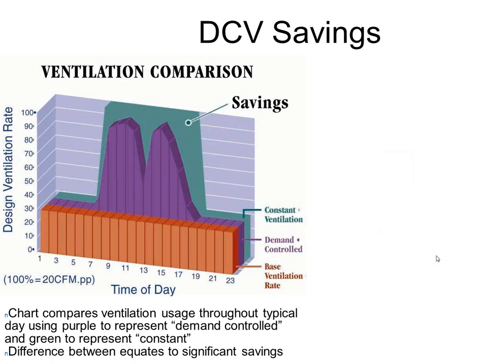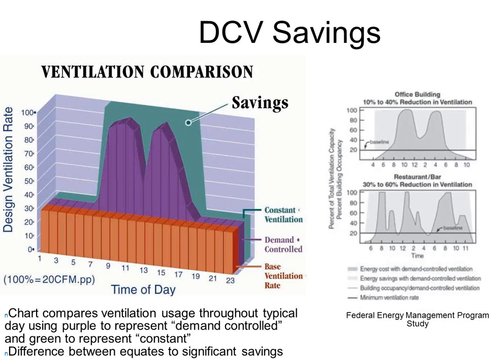This particular one that was on the screen is from a building down in Florida, but this is the same pattern I've had on every single office building that I've ever done. There's also federal study data that shows that same two-hump profile for office buildings. It's very predictable, and the first hump's always taller than the second hump. If you got a restaurant situation, you get the 3 humps, breakfast, lunch, and dinner, and you get that little bonus hump afterwards when you get all the people that don't like crowds going there, right?